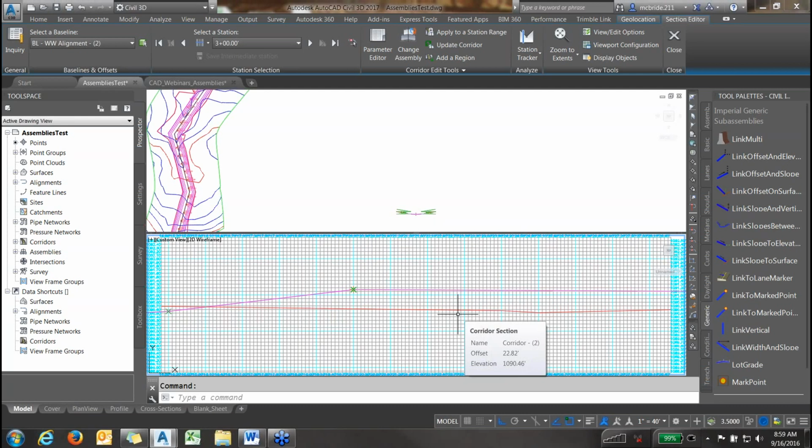And this is good because if you're dealing with any kind of water that needs to get in from the right side, what you don't want to happen is have a 6-to-1 slope to where it can't cross over to get into the waterway. This flat section basically says, okay, it'll still get in the waterway, it's just going to be a little flatter slope to do so.